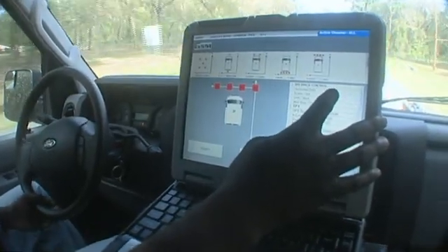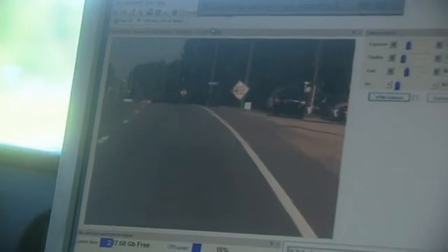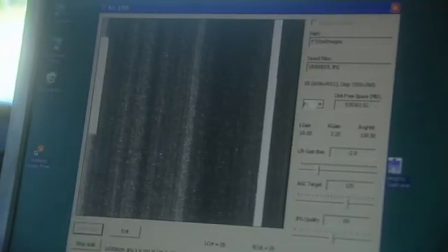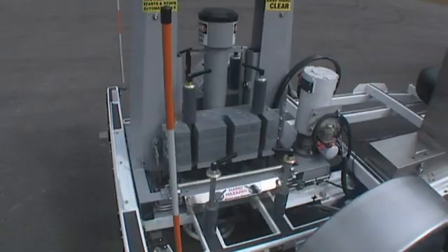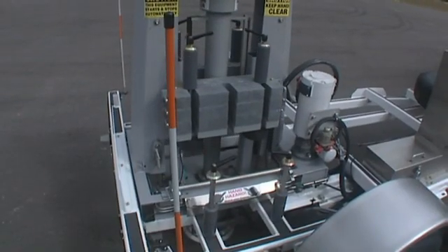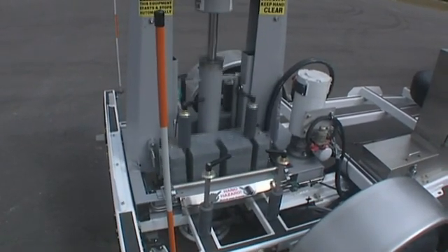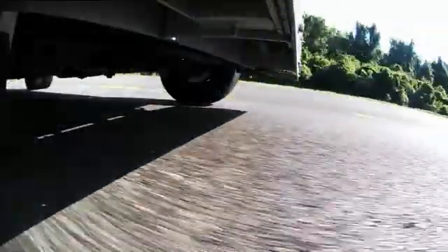It helps us engineers visualize the vast amount of data that we can collect with the state-of-the-art non-destructive testing technologies. It also allows us to collect much more data in a very fast manner in a very short amount of time. The examples I gave you so far are only related to the falling weight deflectometer and the ground penetrating radar that we frequently use here at the Florida Department of Transportation.